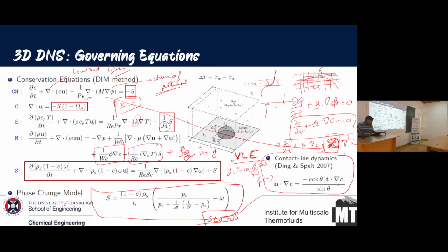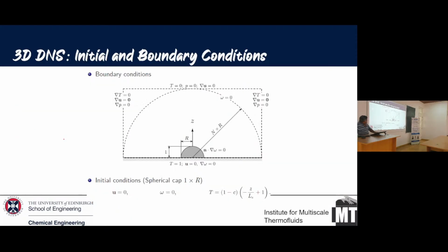Here you can see it's a transient model. You've got a three-dimensional space parameter here, so everything is done in 3D as well. An important thing is the boundary conditions. Obviously your temperature is constant. This is a hot wall, so we don't use a heat flux condition, we use a temperature condition here. The next important question we ask is, what should be the boundary conditions at the top? How high should your box be, and what could the boundary conditions be?